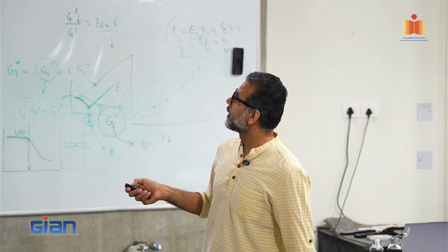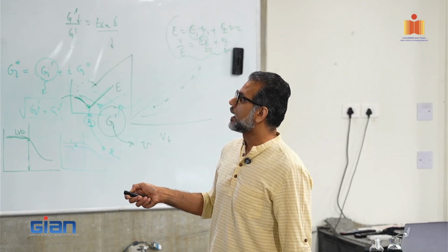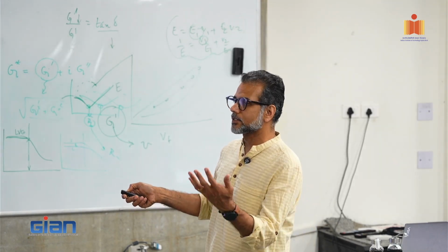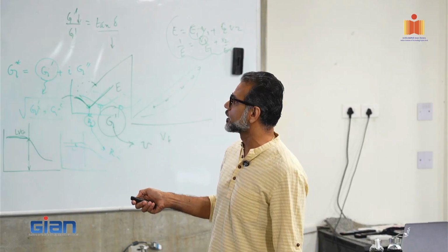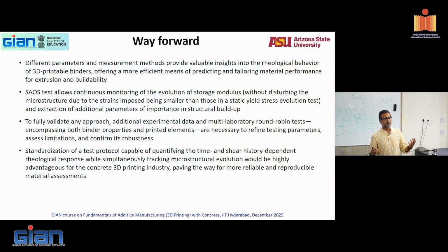So, way forward, different parameters provide valuable insights. The small amplitude oscillatory test, the oscillatory rheology that I told you about, allows continuous monitoring, so it's good. To fully validate any approach, you need lots of data. We don't have that much experimental data. Standardization of test protocols is very time consuming, but doing that would be highly advantageous for the industry, paving the way for more reliable standards.